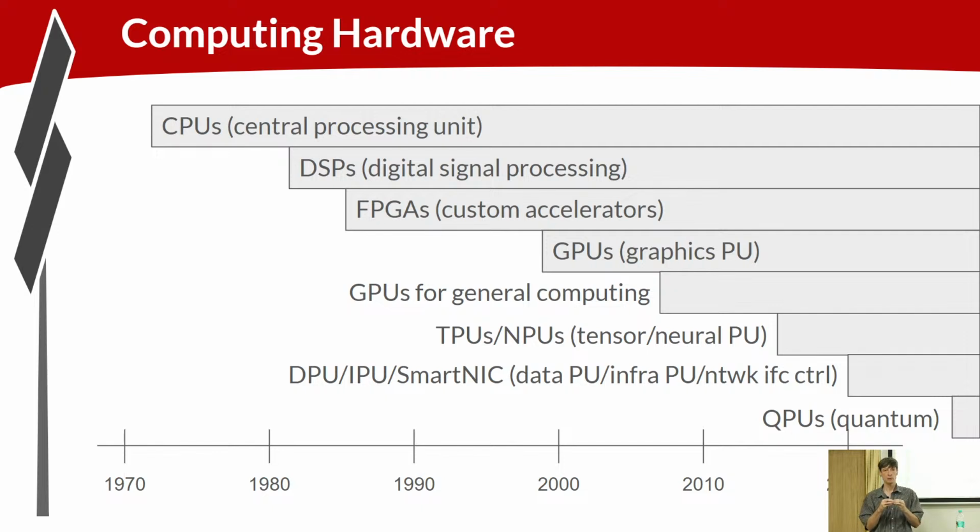The technology trends pushed us to a place where interconnect delay was more substantial than the delay through logic gates. These big complex cores, since they're big, have a lot of routing, a lot of delay from the routing. So those trends pushed us back toward tighter, more compact cores being more performant. The industry overshot. We made these cores too big, too power hungry, too complex. So all the innovation in CPU architecture for the last decade or more has been about what we are going to throw out, and people are writing research papers about this brilliant idea to get rid of an idea from yesterday.